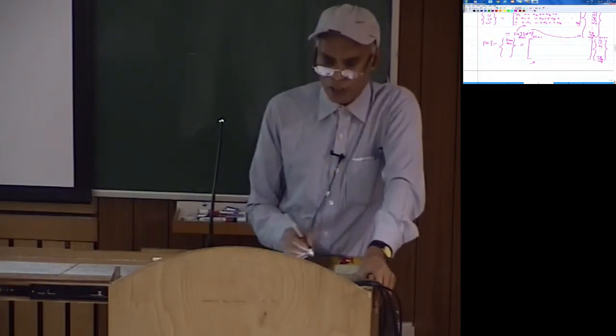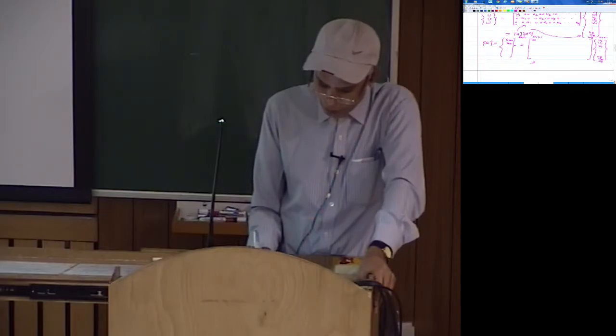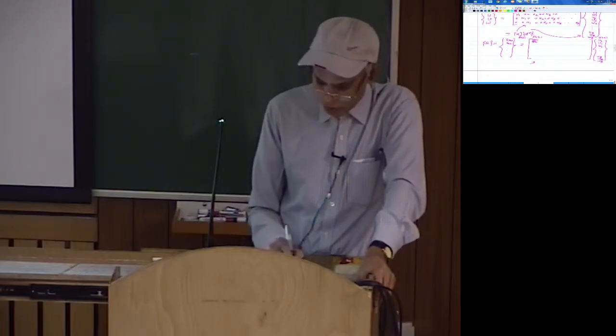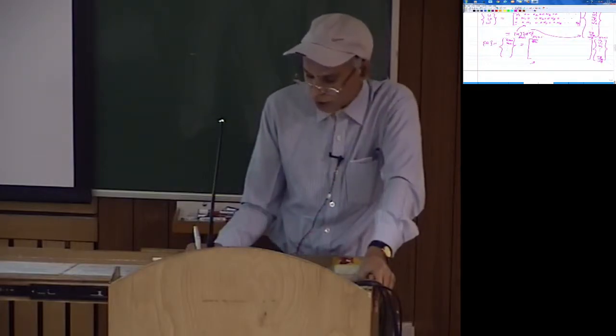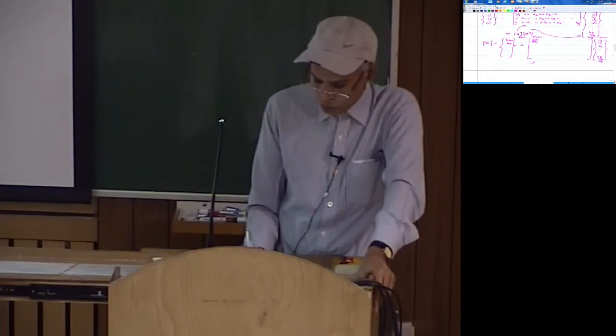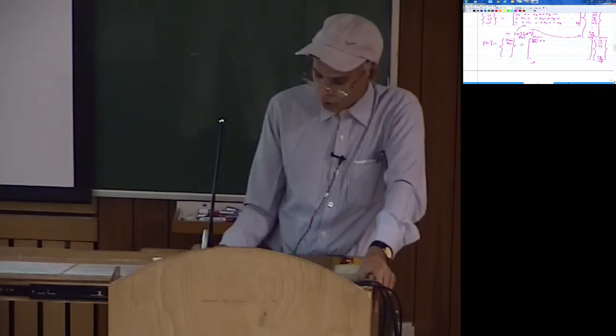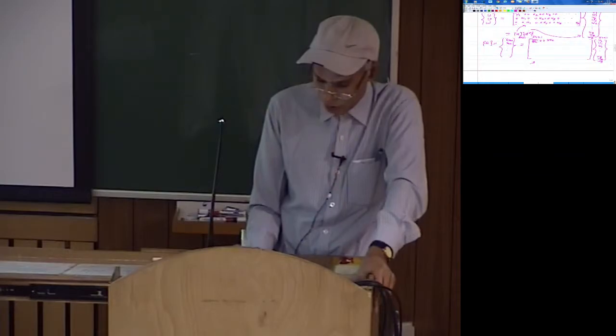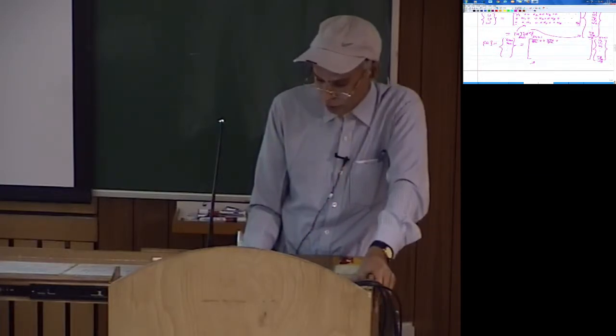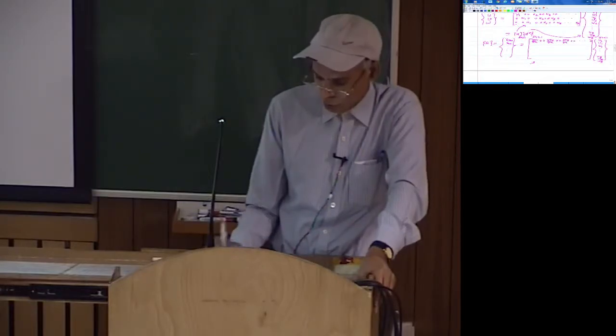So epsilon xx is del u by del x. So I can write that as del N1 by del x into u1, plus the next term would be del N2 by del x into u2. So I put 0 0 here because in the multiplication, the v1 and w1 do not contribute, and then you will have del N2 by del x 0 0 and then del N3 by del x 0 0 and so on. The last of course would be 0.